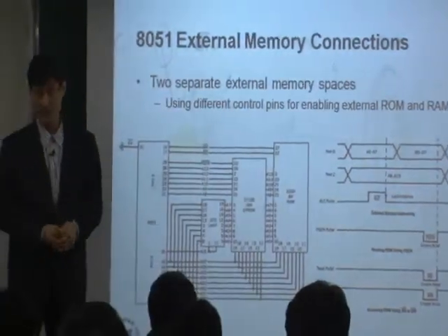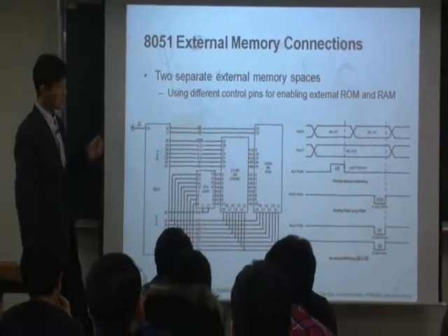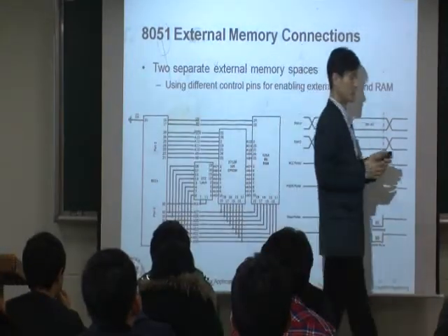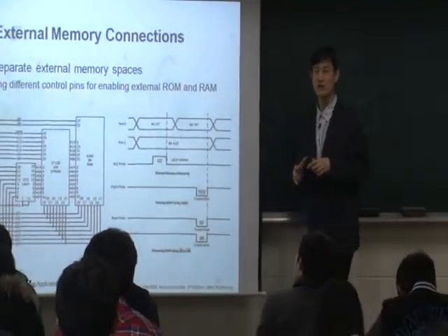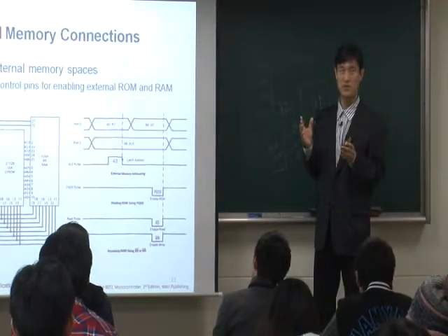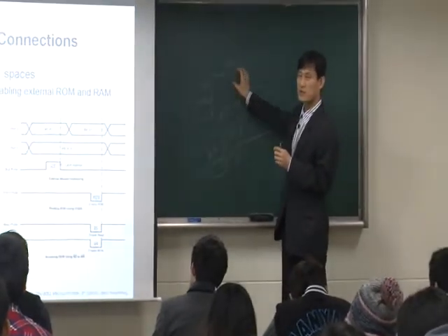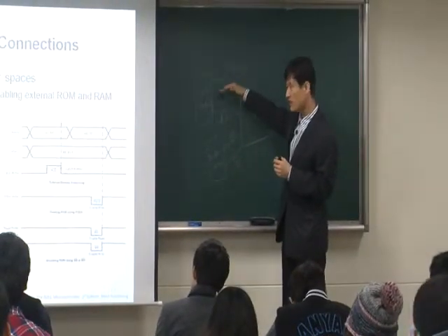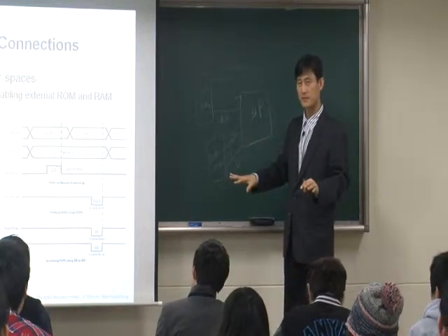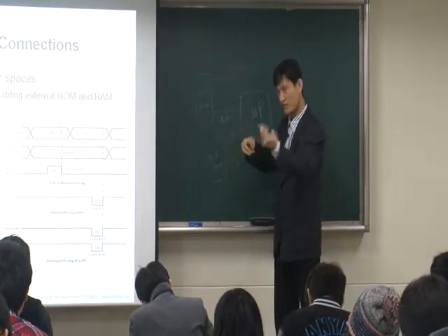Okay, that's something that you probably want to understand in 8051. So now, in order to understand this one, actually these days, like right now, we are using 32-bit processors. Like Intel processors, sometimes they're 64 bits. So these days, pretty much the processors use this way. Instruction path, the address path and data line, these two are separated. Okay? Only that way you send the address at the same time you get the data, right?